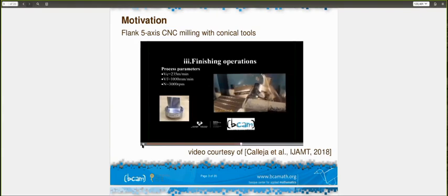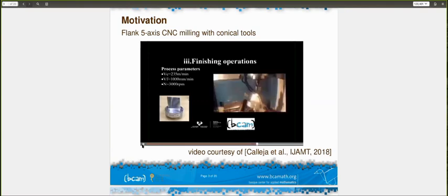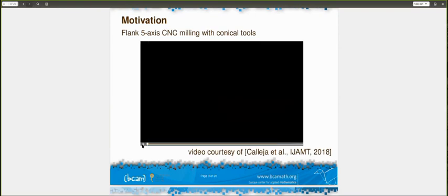And here is the finishing operation, the third one and the most important one. We should control jerk values over the motion, because if we have a variable jerk, it means the tool has some impacts on the surface and there are kinematic issues on the machine drives.